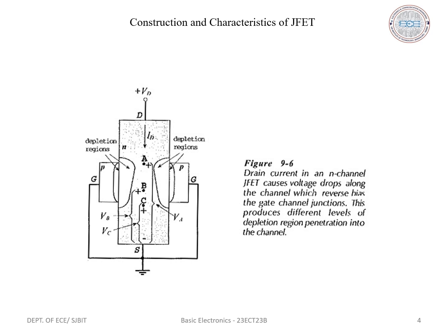due to the applied negative voltage, the gate channel PN junctions are reverse biased. The channel is lightly doped compared to the gate material, so depletion regions penetrate deep into the channel. When the depletion region width increases, free charge carriers are removed and it behaves as an insulator. The width of the channel is narrowed, its resistance is increased and ID is reduced. If a negative VGS is applied and increased further, the depletion regions meet at the center of the channel and